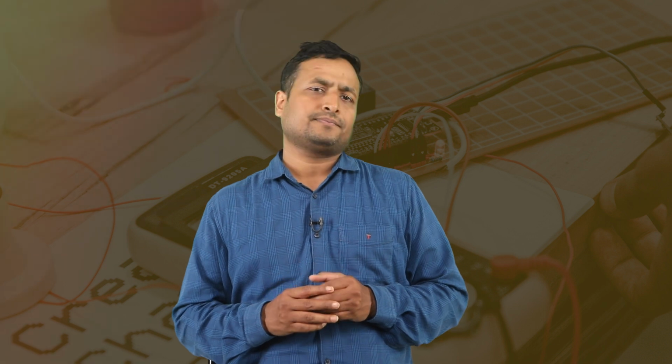Now, what are the testing considerations here? These relays undergo rigorous testing including functional, timing and impulse voltage tests. These tests ensure that the relay operates correctly under fault conditions and meets industrial standards such as IEC 61850.